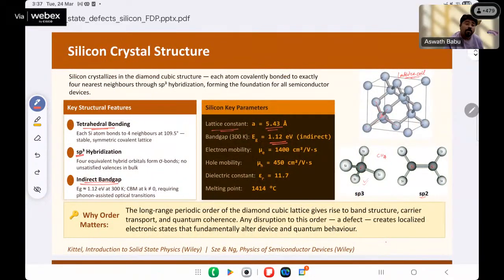Just like a diamond having a nice structure, in a similar fashion, silicon will have such a structure. If you dope with phosphorus, which is a pentavalent, abundant free electrons are going to be added. Those are going to create some kind of interesting quantum behavior by altering the band structure of that material. Not only pentavalent, if you dope with boron, a trivalent atom, they need an extra electron because they only come with 3 electrons. They need 4 valency electrons by nature, very close to silicon behavior.